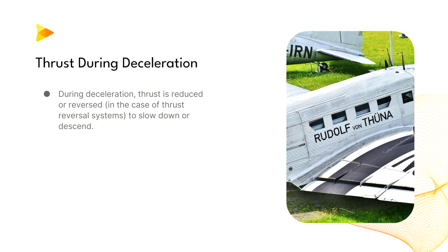So when you decelerate, it means that thrust is less than drag. To a certain extent, drag force will be lessened as the aircraft slows down. So when drag is equal to thrust, the aircraft stops decelerating and stabilizes at a constant airspeed.